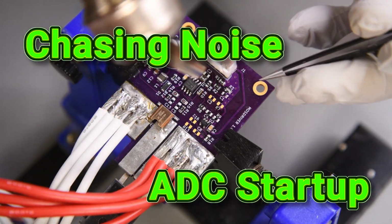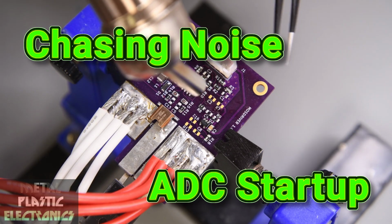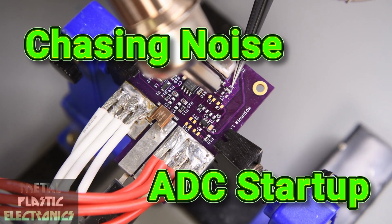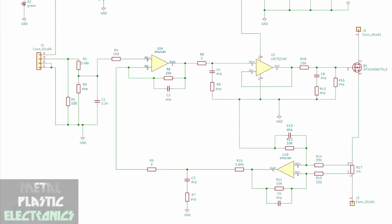Last time we saw our MOSFET power module, it had a frequency response problem. The gain almost doubled at 48 kHz, and I think that could cause me some trouble. While I didn't have space for a high-pass filter in the drive loop, I did have space for a low-pass filter at the input, before the feedback enters the equation. So I decided to put a 20 kHz RC filter at the input.